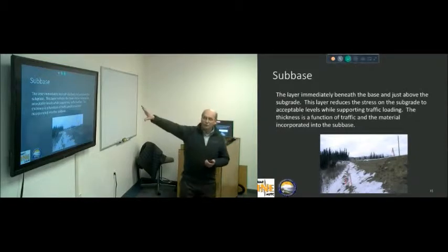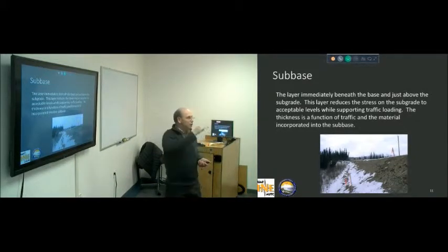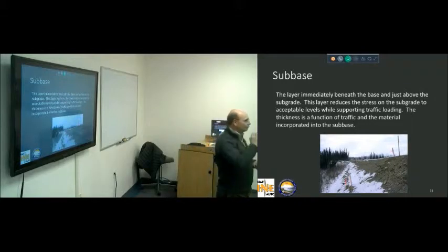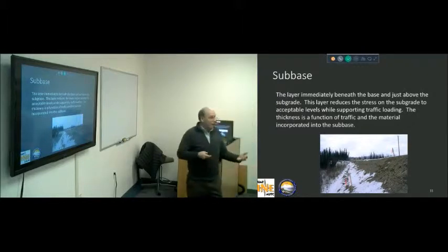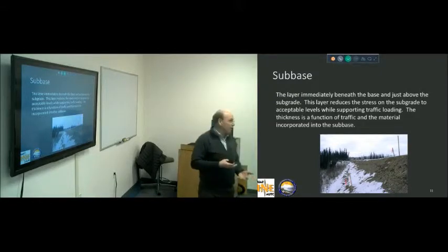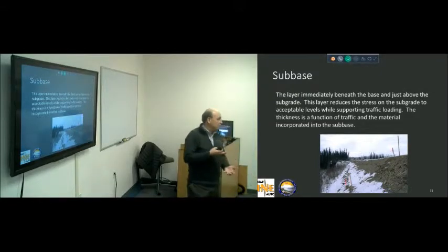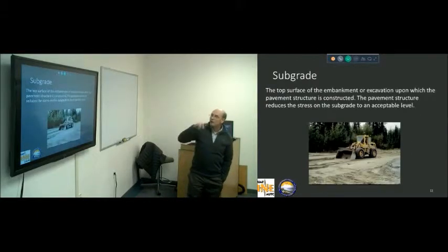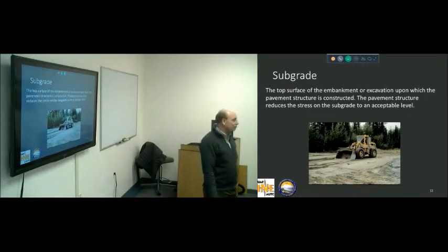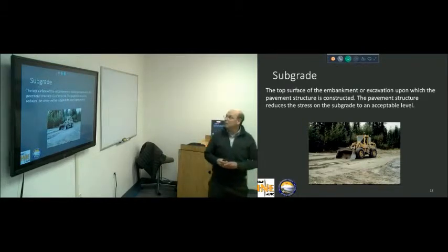But again, the sole purpose of the subbase is to reduce that stress on that subgrade level to the point that it can handle it, whatever the material that might be. If it's silt, then my pavement structure is going to have to be stronger than if it's good, solid, competent gravel. Okay, so there's a difference in there. Okay, subgrade, as we talked, is the top of the embankment or excavation upon which the pavement structure is constructed. Again, that's a little bit of a difference.